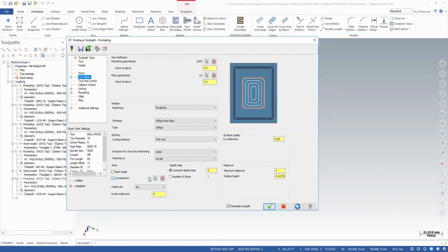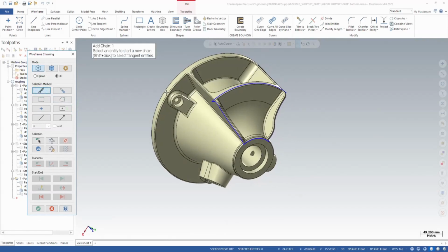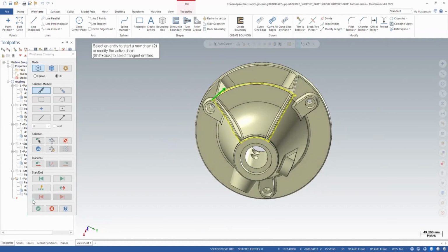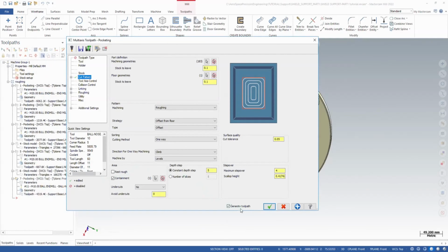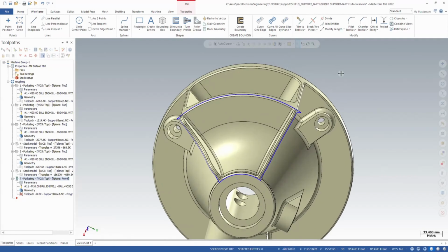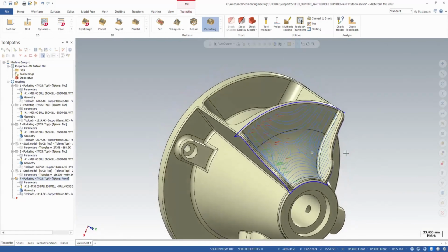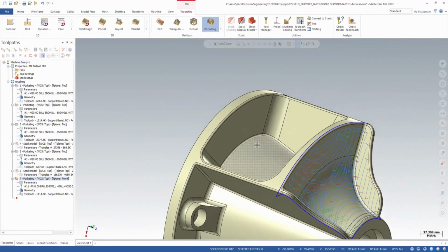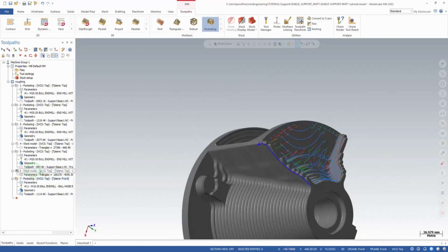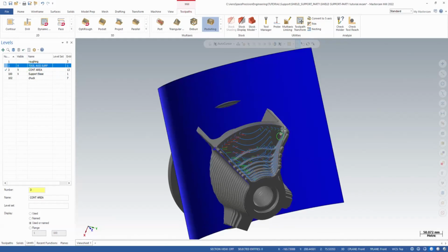This is how it looks on the 3D model. You can see the 3D model. We created the containment wireframe. Let's go to the toolpath parameters, then click the cut pattern page, then click the containment wireframe. We already created the wireframe previously. You can change the selection. It must be a closed chain. A closed chain is the green color chain. Now let's generate again and see the result.